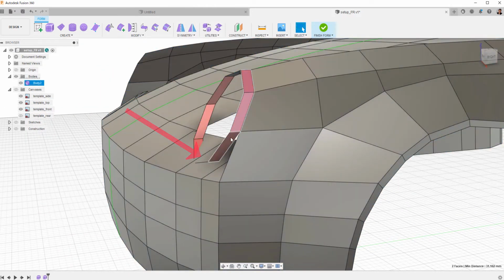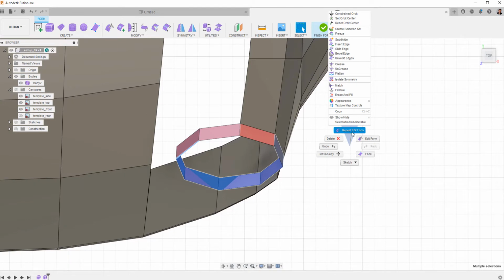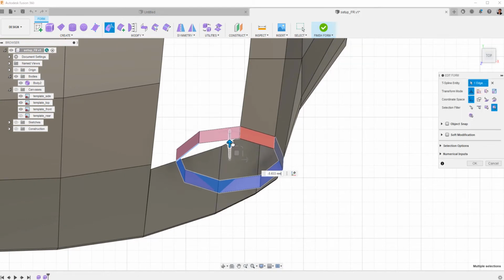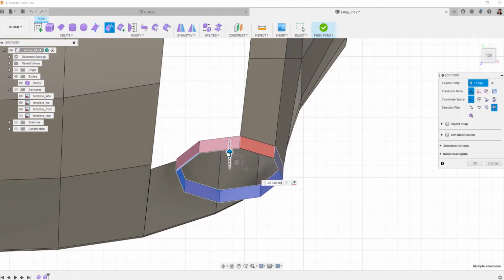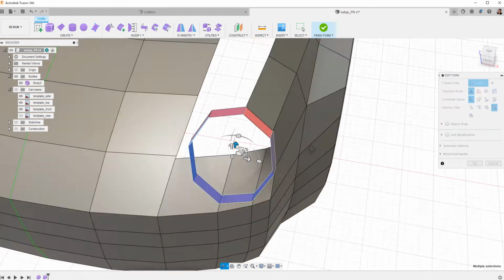If separate objects are to be merged, they need to be in the right positions to merge properly. In this case, the bumper position is fixed and the best position is adjusted on the lamp cylinder side. When moving the cylinder, be sure to check that the edge flow is smoother in each view.